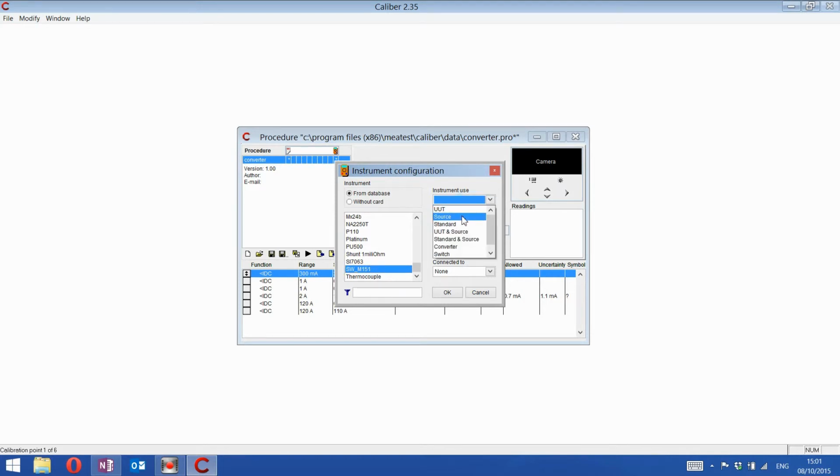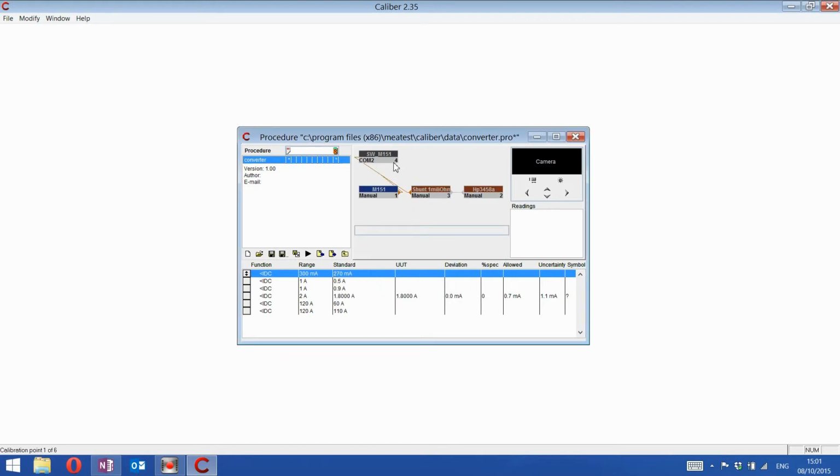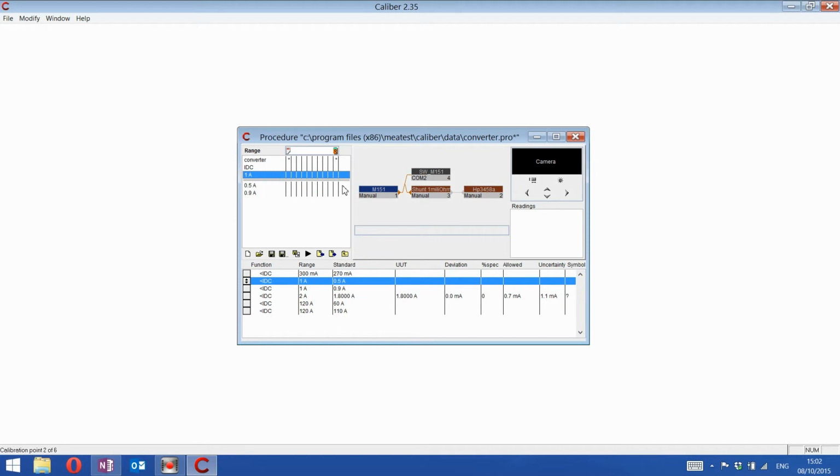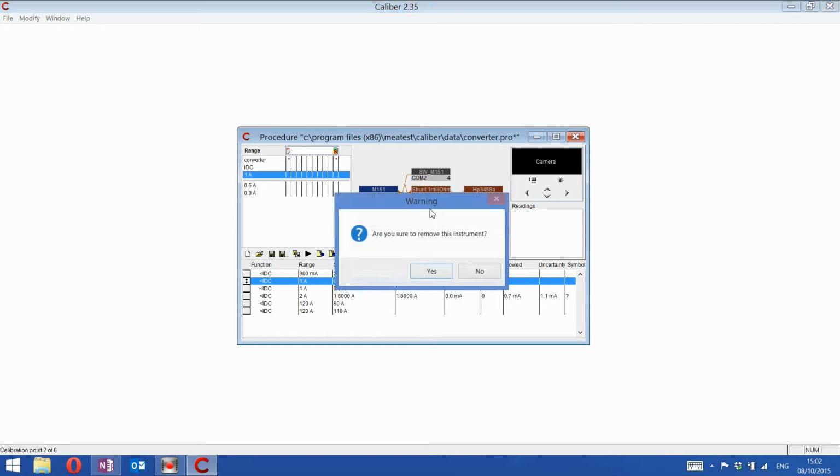Let's assume I have a very simple switch with serial port. If you send it message A, it connects input and output directly to work like a cable. If you send message B, input is connected to shunt force terminals and output to sense terminals. Here in lower ranges, I will remove the shunt and connect the meter back to master bus.